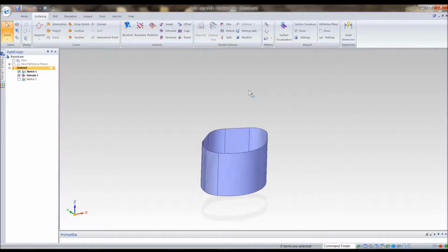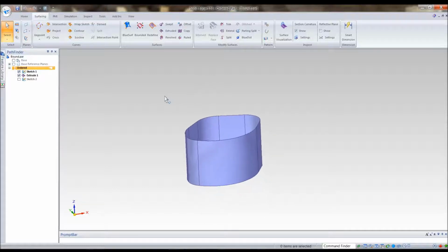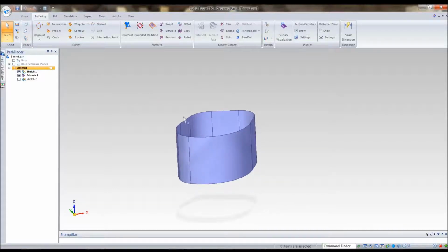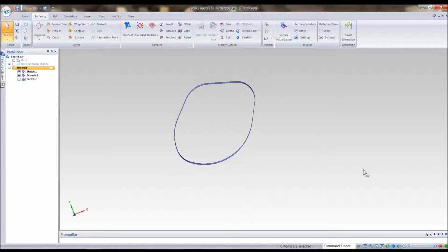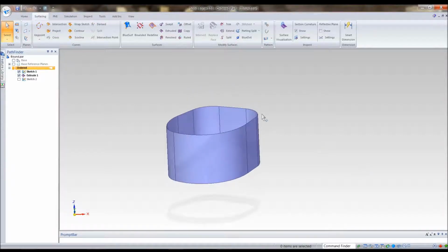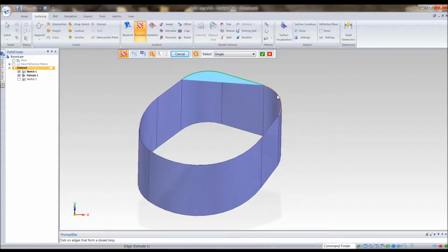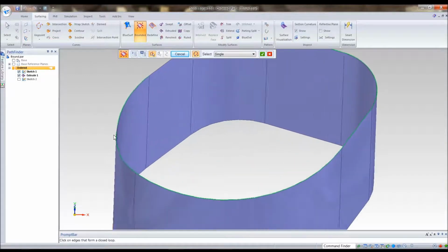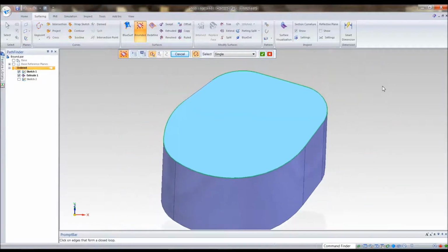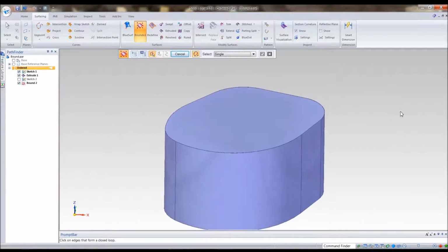We're going to stay in the vein of the bounded surface functionality in Solid Edge just to show you one more enhancement in ST6. I've got this surface. Basically I created an extruded surface with this sketch, and I'm going to go ahead and create a bounded surface again with the closed boundary turned on, and I'm going to select the edges of this surface, and you can see it's filling it in for me as I go along. And so I've committed and I've got this surface.